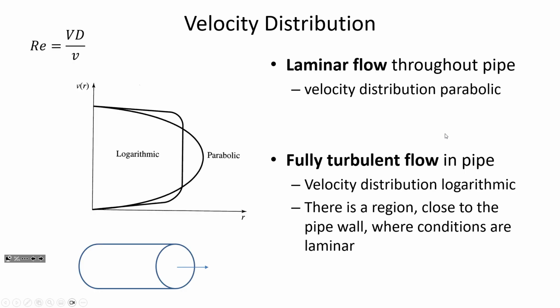Okay, so velocity distributions describe the fact that there isn't just one velocity in a pipe. There is a variety of different velocities in a pipe depending on how close you are to the edge of the pipe. And we talked about this a little bit on Wednesday, how when you are really close to the edge of a boundary that's not moving, whether it's a river bank or whether it's the wall of a pipe, the liquid velocity is 0 in the immediate vicinity of that stationary object.